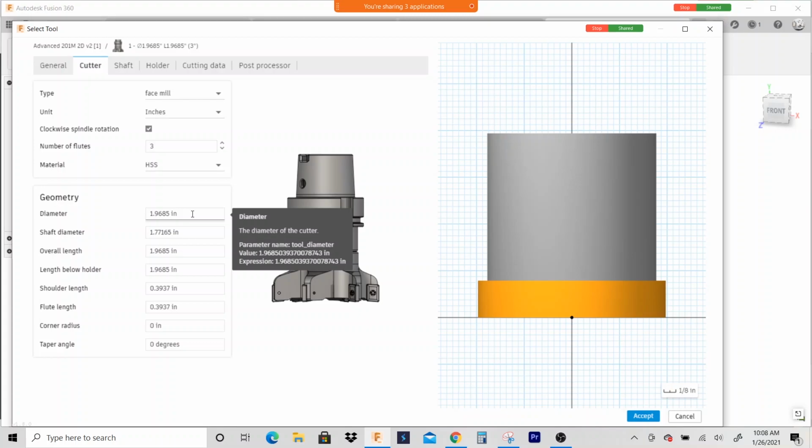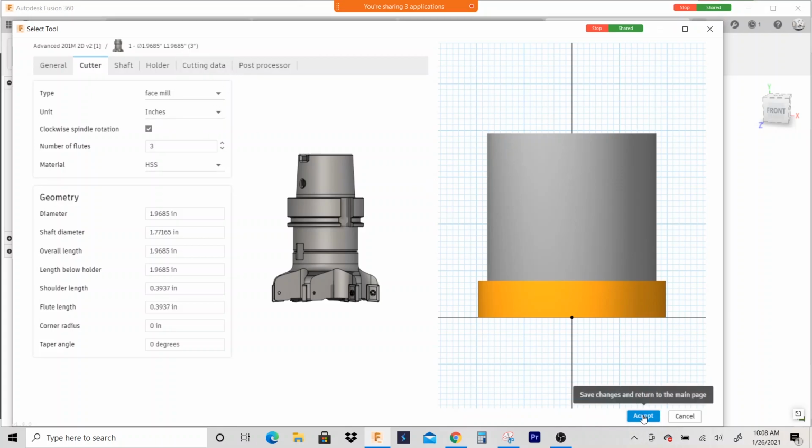Where it meets the intersection, it comes out. The tool chatters like crazy, man, and it has a half-inch. You're supposed to use a 1-inch tool to cut it, but all the 1-inch tools I use would chatter, and I had to get another tool, but there was problems with that tool because the chamfer has to be a half-inch, but the tool would only go. The inserts were only like 0.35, so I had to do this weird step down, like 45-degree step down.